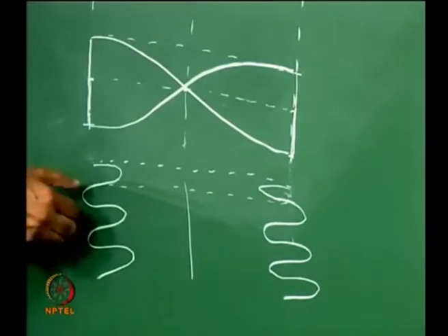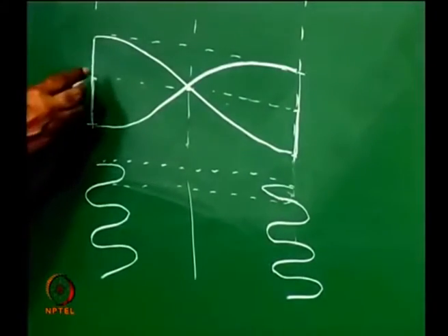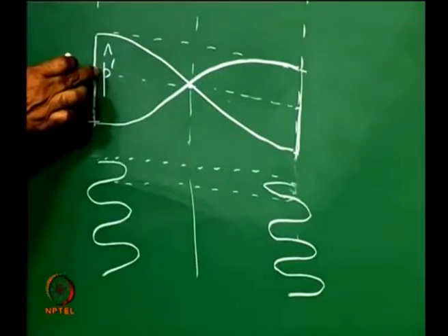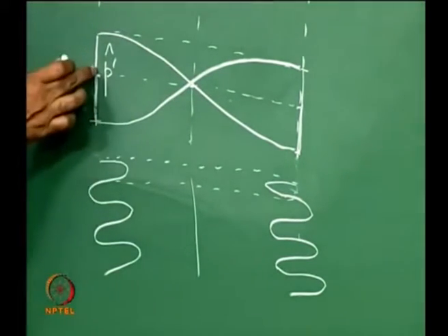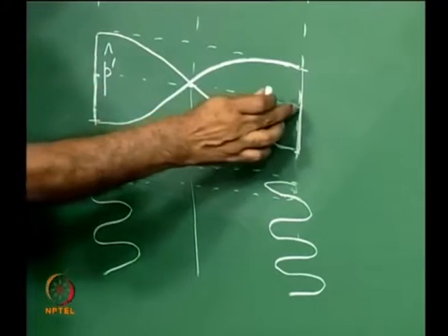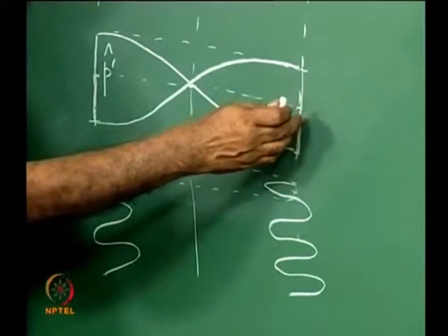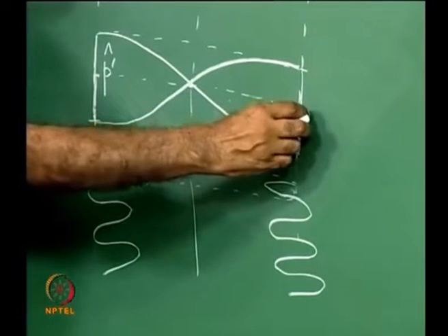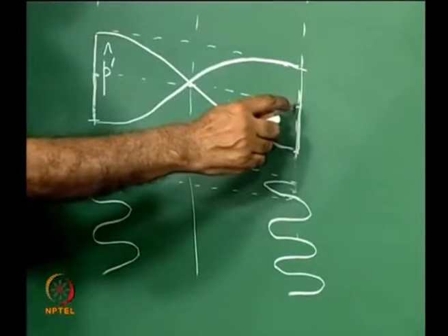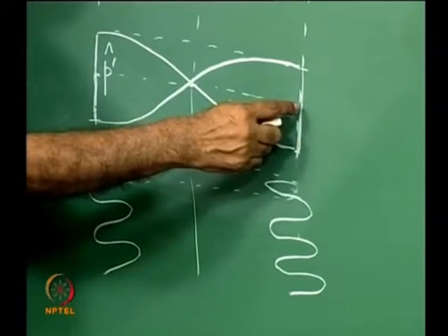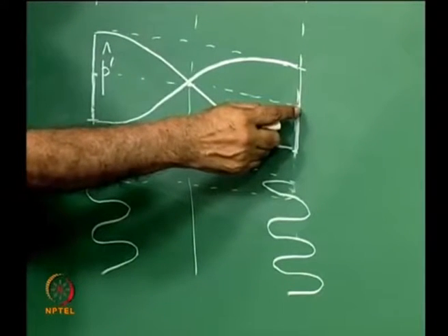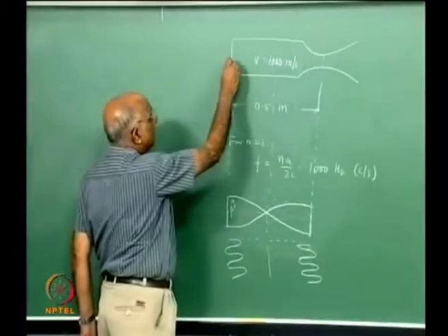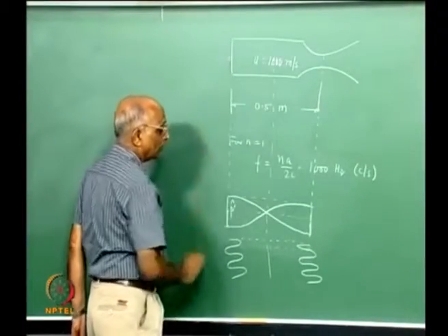What is it we also find over here? When the oscillation in amplitude p bar is maximum and positive in this case, the amplitude of oscillations leaving the nozzle is negative, and therefore the thrust of a rocket motor depends on the pressure at the nozzle, so the thrust oscillations could be out of phase with the pressure oscillations as you are measuring at the head end of a rocket motor.